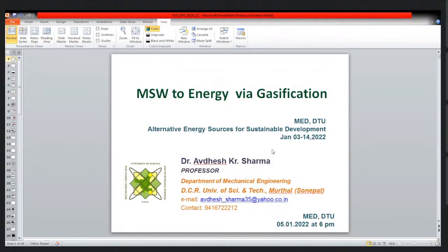From what I am observing, I have used biomass plus RDF. RDF is nothing but municipal solid waste, and municipal solid waste contains plastic itself. Some people have done experiments on gasification using plastic waste, and they observed that the hydrogen component, which is the more important part of the producer gas, is higher when the plastic was burned together with the biomass or any other waste.